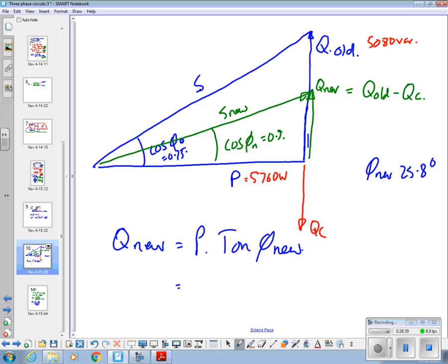That is 5760 times tan 25.8 degrees, and the answer came out at 2784 VAr.